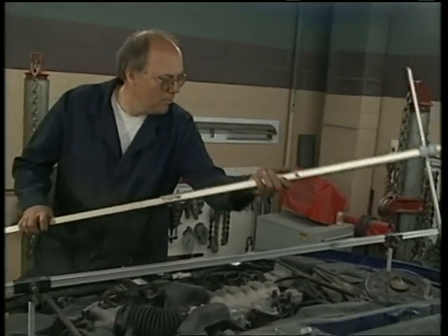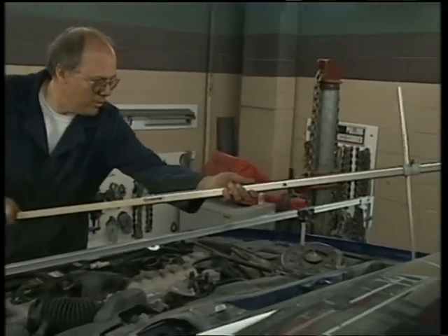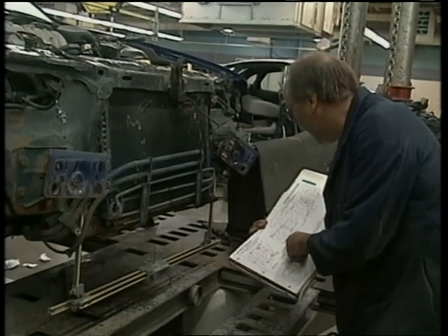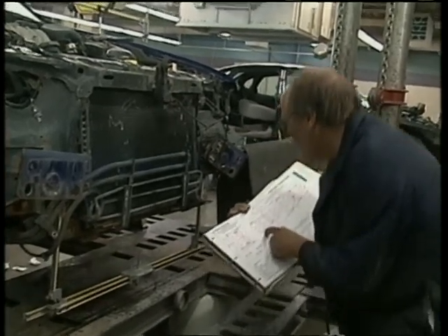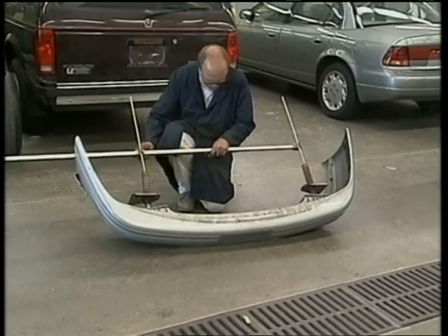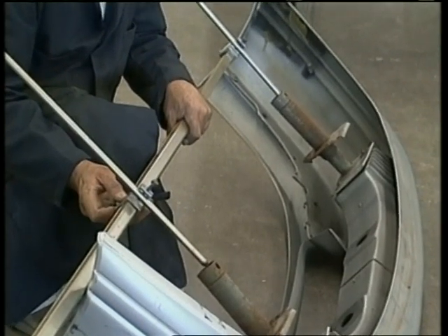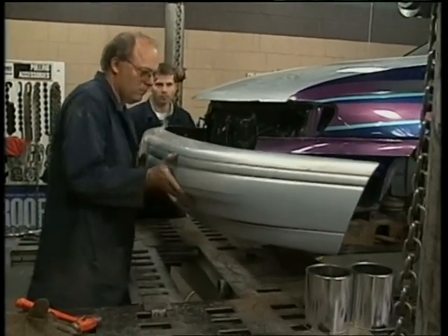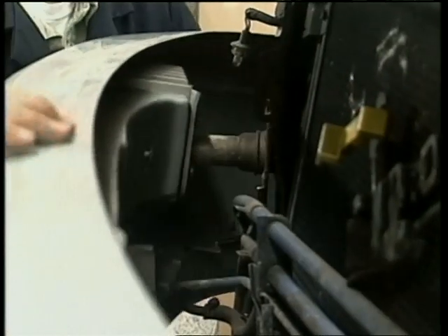Once all straightening operations are complete, make final alignment checks. Measurements of all dimensions should be made and checked once more against the body dimension book. Your work can also be referenced to the undamaged side or checked with new or undamaged parts. After frame alignment, fixtures and parts should line up and should not have to be forced or hammered into place.